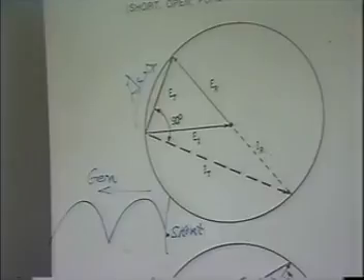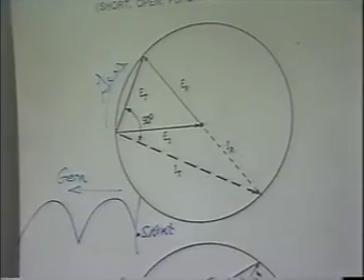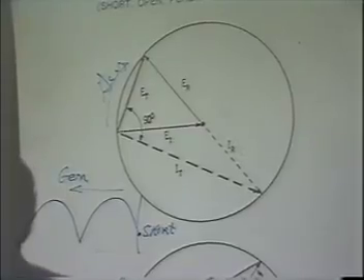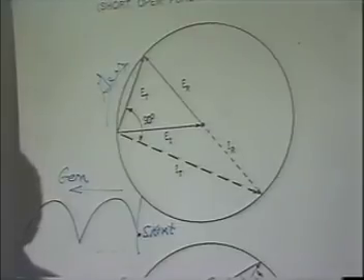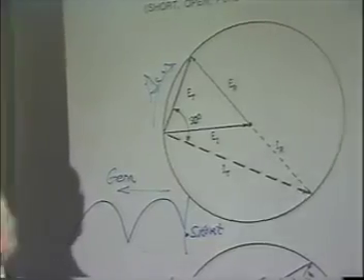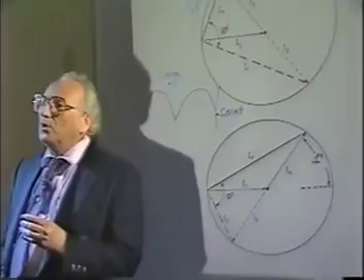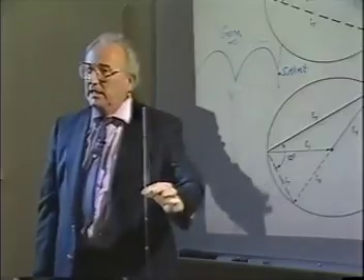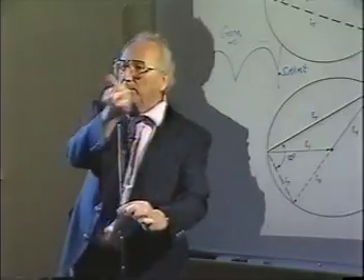On the transmission line, there are two signals traveling in opposite directions. In the textbook, if you read that chapter, there's a whole page of diagrams that shows you the two signals, one traveling to the right, one traveling to the left. After that particular page, I said that if you want to show a phasor diagram to represent that, here you have two signals, one going this direction, one going this direction. In order to have a diagram to represent the same thing, I must fix one of those in position and make the other one rotate.